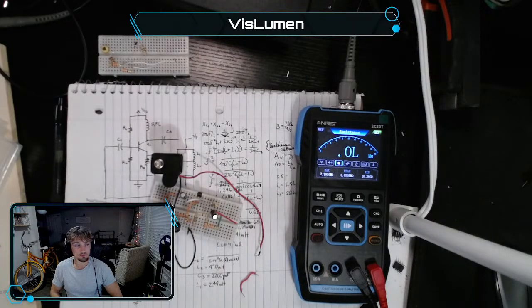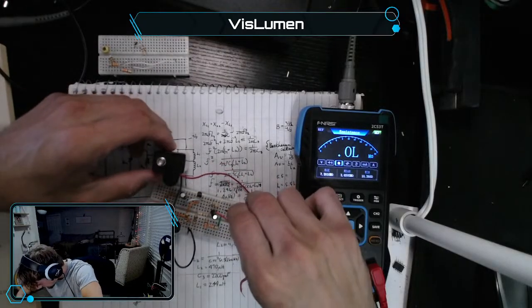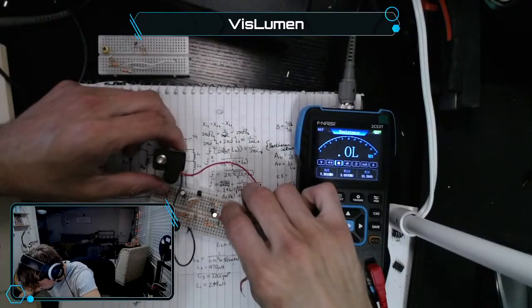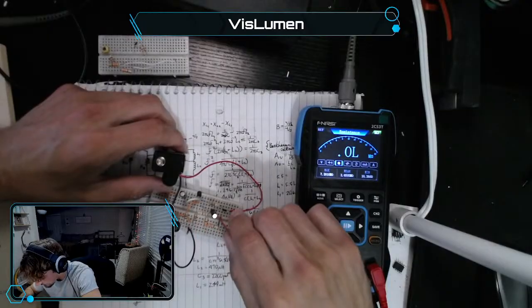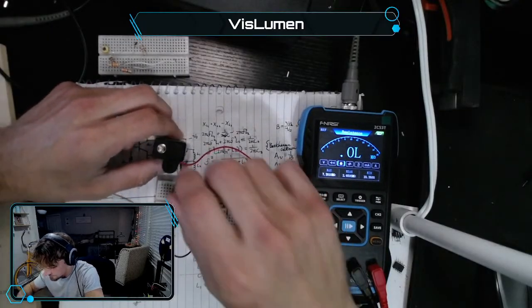Okay, so higher frequencies get through easier. I say whatever. Let's try it. Okay, and then that's going to be our input. Right at the 68, and right to our voltage divider. 68 ohms. Straight to the collector of our transistor.